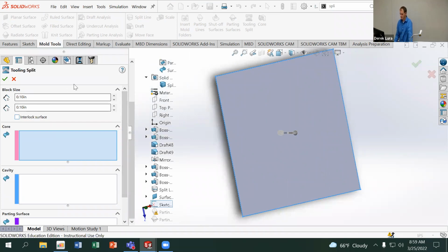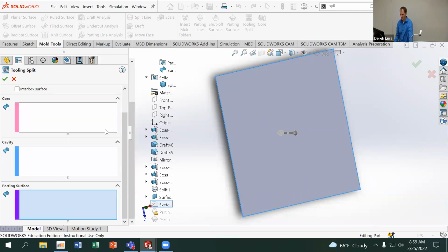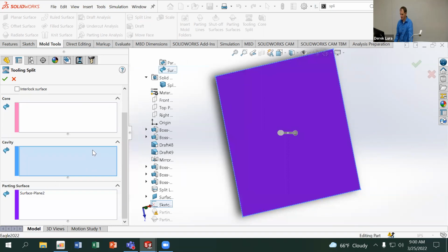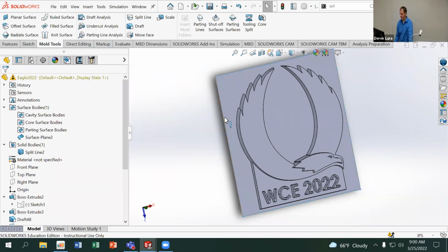There, you can open solid bodies and then right click on the split line to control line and then show. Yeah, but it's not letting me add to the cavity though. Oh, I see. I think I need to turn. Yeah, I need to generate surfaces from that body.